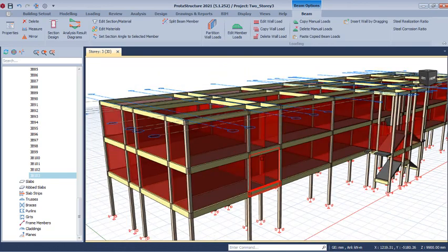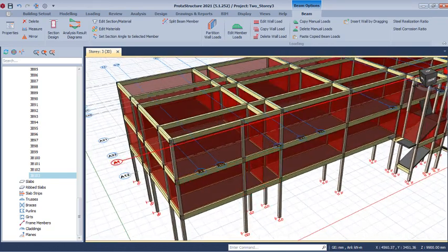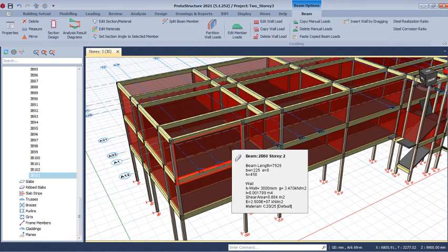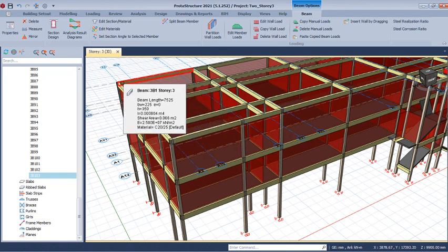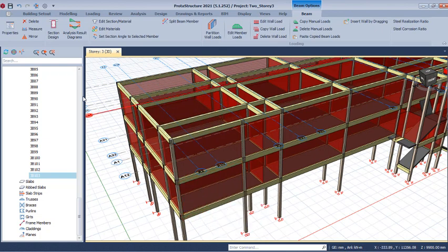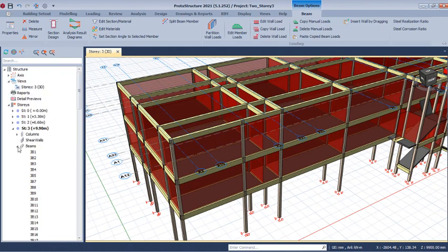The next thing I wanted to show, although it is most important when you are designing a high-rise structure, is to anchor the reinforced concrete beam to the column, or what we call anchorage. I will be demonstrating that now. So I will navigate to the plan view of any of these floors. You are supposed to do this for all of the floors.